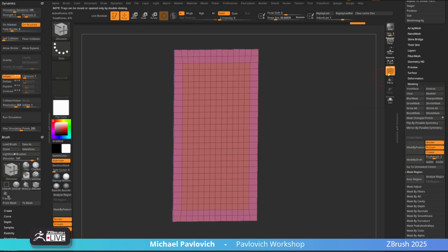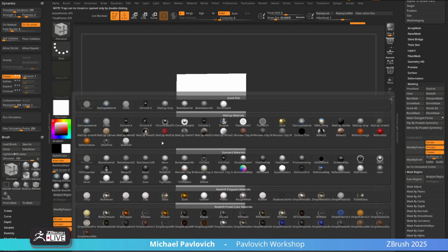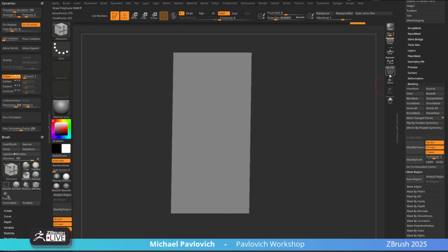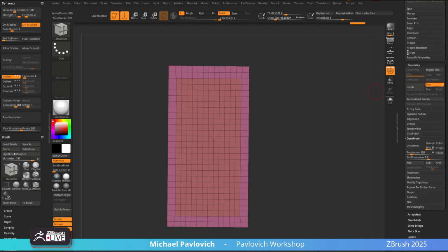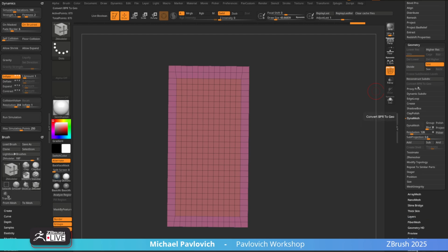Now, it did what we wanted. I just want a little bit more resolution. I'm actually going to switch back our material here to, I don't know, Madcap Gray, I guess. I want more resolution. Now, just like we did before, let me switch here, just so you can see a little bit better. I'm going to go through here, and just like we did, I'm going to say geometry divide, and I'm going to turn off that smooth.